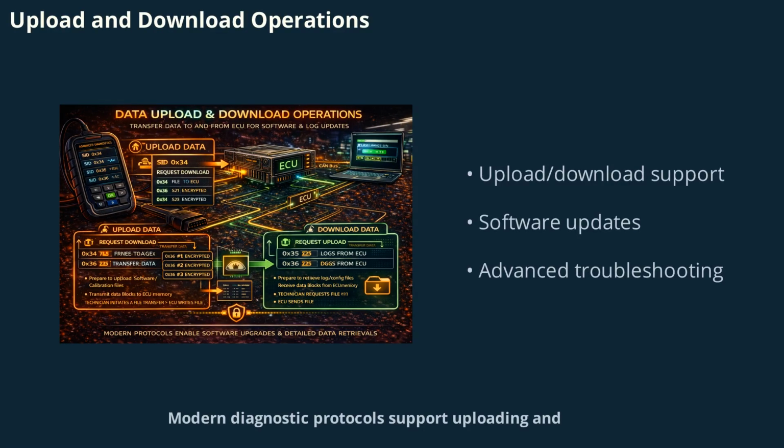Modern diagnostic protocols support uploading and downloading data to and from the ECU. Services like request download, request upload, and transfer data enable technicians to update software, calibrate parameters, and retrieve logs. These operations are vital during vehicle development, software updates, and advanced troubleshooting, ensuring that the latest configurations and data are always available for analysis and improvement.